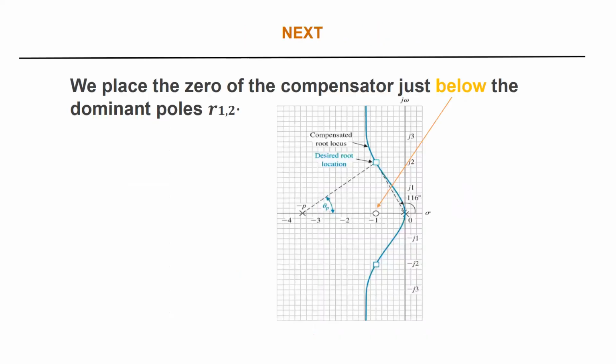And if we add those two, okay, this is the original system. I have 2 poles, and now I'm adding 1 zero here and 1 pole here. The locus is going to be, this pole will go to this zero, and those will bend and go in this direction. And we would like to force it to have 1 pole here and the other one in here. That's minus 1 and j2.